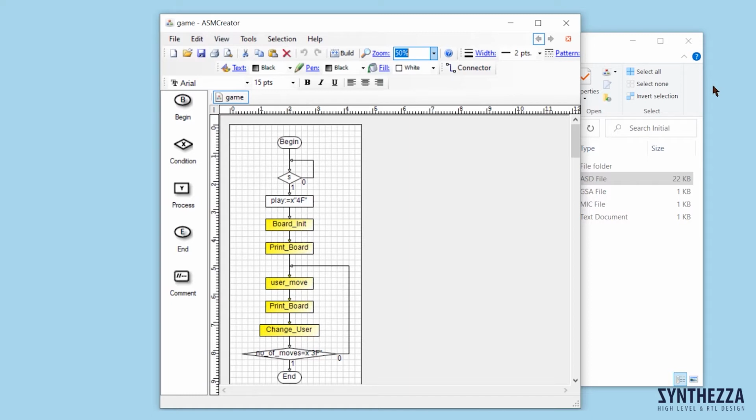There are two kinds of micro-operations in ASM. The first kind is a simple micro-operation containing the assignment colon equal. The second kind of micro-operation is a component micro-operation. We call it a sub-ASM or generalized operator. Such a micro-operation doesn't contain an assign operator colon equal. In this example, they are colored yellow, but the color is not essential. These operators are sub-ASMs, even when included in the mother ASM to get the whole behavior of the digital system, or one of its modes if you would like to present them separately.